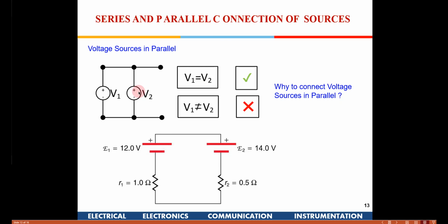So my next question was, why at all do we have to do this? Is there any advantage in having these two voltage sources connected in parallel? Sir, if one voltage source dies out, the other still keeps working. Yeah, okay, let's come to the death aspect later, but when they are living, then what happens? Then if you see, the total internal resistance is reduced. Yeah, I can put it like this, that the current which will be provided by these two sources will be half. Correct?